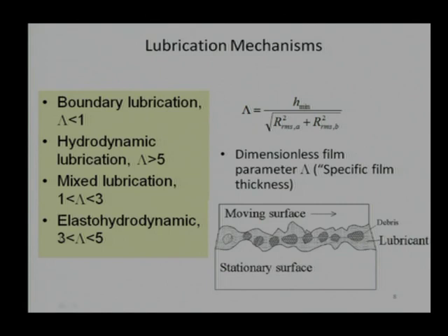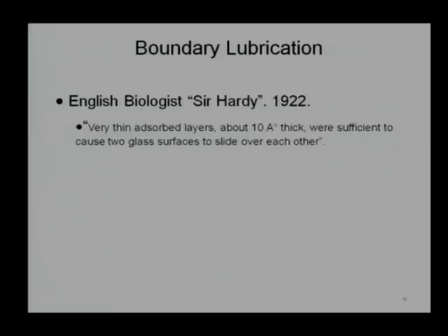As previously it was mentioned, if there is wear generation or particles coming from outside, then it is quite possible that the hydrodynamic lubrication mechanism may turn out to be a mixed lubrication mechanism because of the particles occupying the space, reducing the effective film thickness. That is why EHL will move to the mixed lubrication mechanism. So, we need to keep all the theories ready. Whenever the situation comes, we need to use that theory or a combination of theories, so that we get the overall possible or better solution. Let us start with the boundary lubrication mechanism.